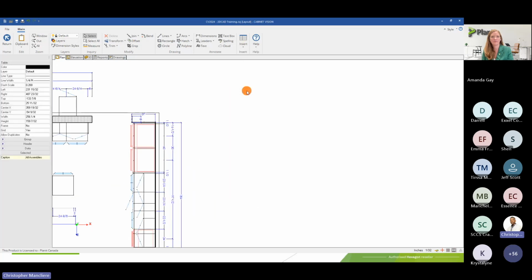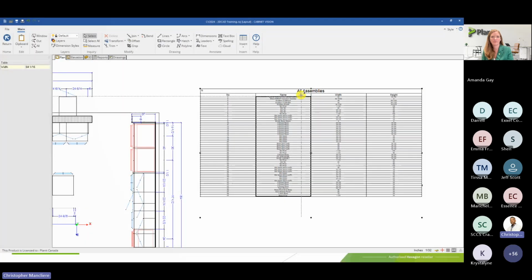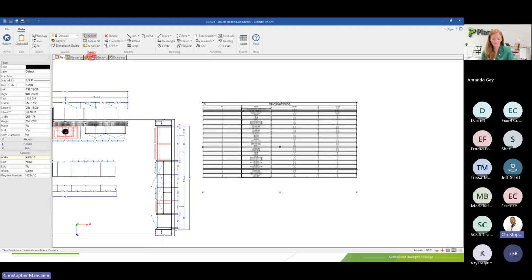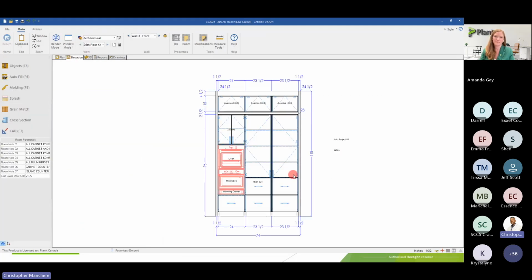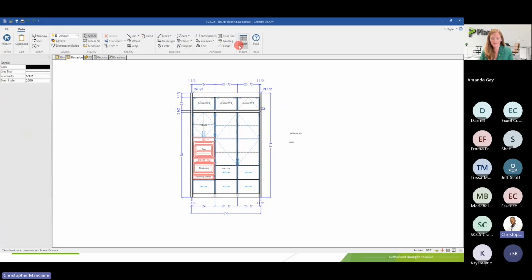And when you select a table, you can individually go rename each column, change the width, the height, as well as the font. So everything is customizable on the left side and directly on the screen, where you can change also the table itself. So it could be a good way, for example, if you are in elevation view and you want to create already a symbol that will be a table with all the cabinets from your elevation view. So you can go in CAD, or just go select all, delete everything, insert a table,